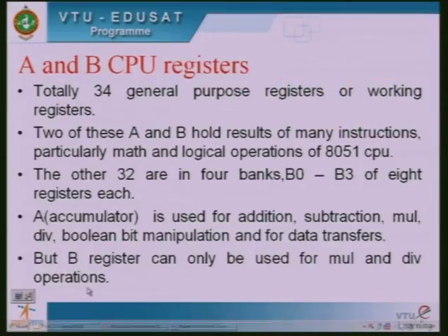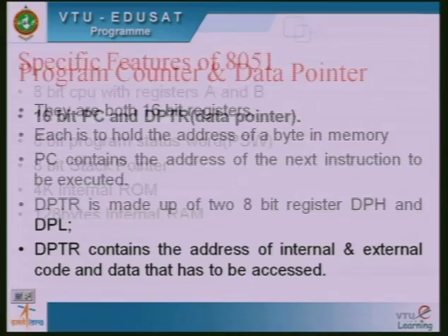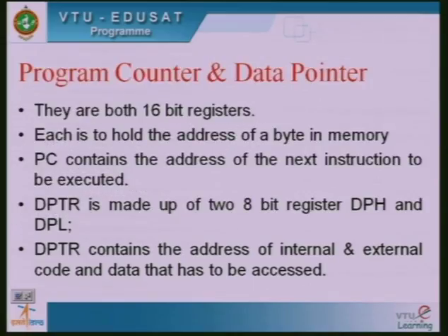And coming to the next registers, they are 16 bits in length, and they are nothing but the program counter and data pointer. And the program counter is nothing but a pointer which points to where we have saved or stored our program.